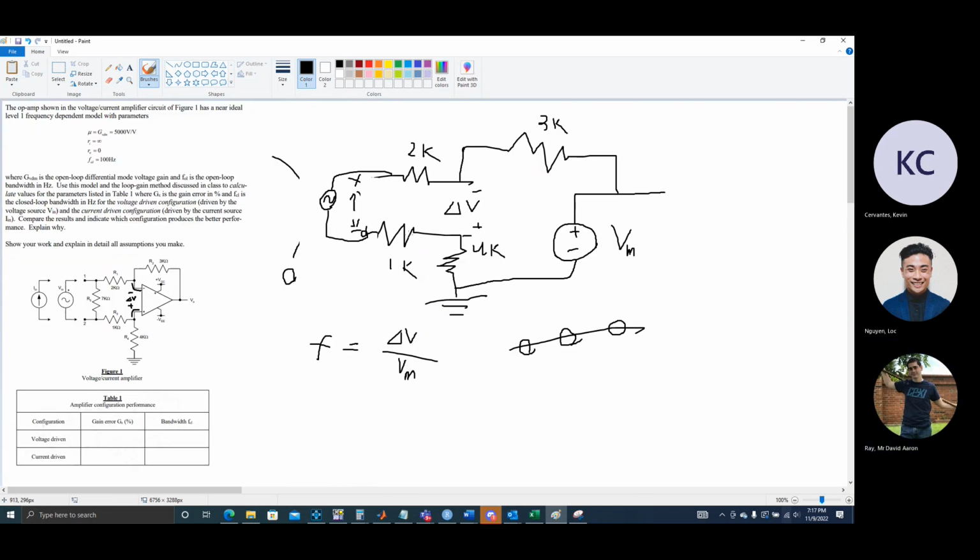There we go. So then we're going to do KVL to find change in V. So we start with, oh, there's the mouse. We see it's positive here. So then we're going to flow counterclockwise. Actually, let's not do KVL, sorry. We're going to do voltage divider because since this becomes just a straight line, now these two resistors are in series. And so then we can add them in series.